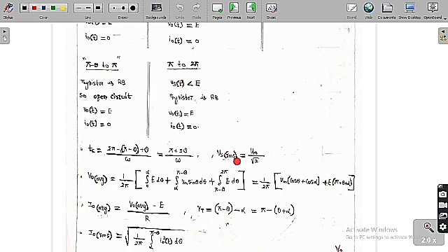So now, if you want to know the source voltage RMS value, it is Vm by root 2. And if you want to know the average value of the output voltage, it is equal to 1 by 2 pi integration of 0 to alpha E d theta, plus alpha to pi minus theta, where it is equal to the source voltage Vm sin theta d theta, plus again pi minus theta to 2 pi, it is again E d theta. So if you solve this, we are going to get 1 by 2 pi into Vm into cos theta plus cos alpha plus E into pi plus theta plus alpha. So you are going to get this complex expression.